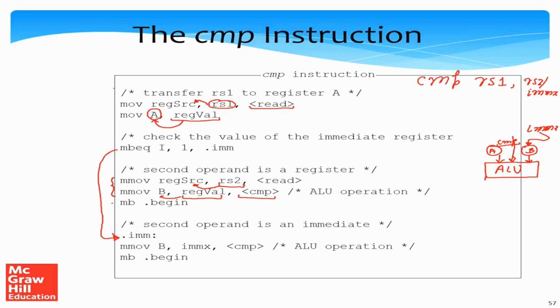And so we are ready with, mind you, when we are doing a comparison, the ALU result will contain nothing. What will happen is that the results of the comparison will populate the flags register. So we can read flags.e and flags.gt at a later point of time to figure out what was the result of the comparison. So the compare instruction will not write to any registers. It does not have any register side effect per se. It will just modify the flags.